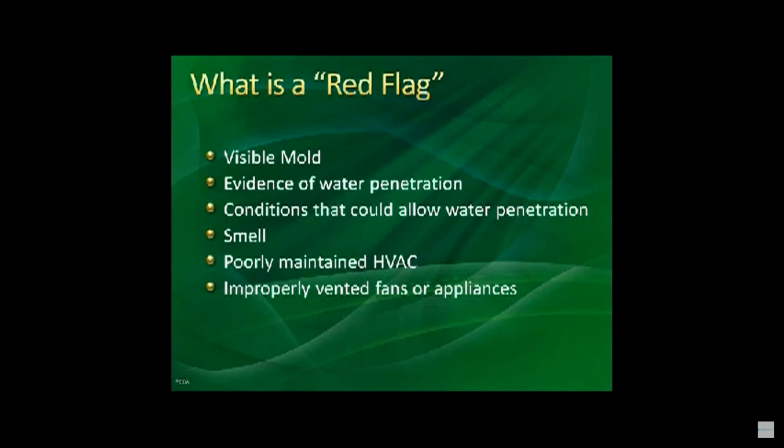Those are defined simply as visible mold, evidence of water penetration, which could be a stain, cracks in blocks or foundation walls, and poorly maintained HVAC systems, heating, ventilation, and air conditioning. You pull out the filter and there's a big hole through the filter, and you look in the return and you see a lot of mold, well then it's circulated through the home. And again, you've seen the pictures of the improperly vented fans and appliances.